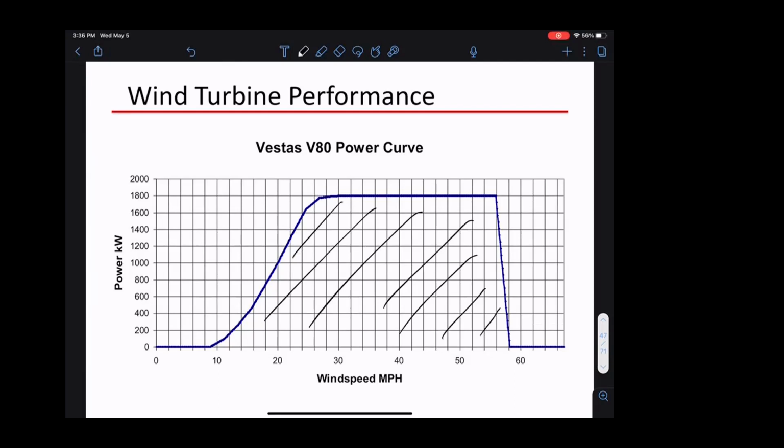So wind turbine generation is not entirely uncertain. You have some ramping capabilities, but your ramping capability is limited by the wind speed you're experiencing. Based on your wind speed, you can ramp somewhat, but not arbitrarily, and this depends on the external speed you have from wind. Any questions about these operating characteristics? Okay, so these are our operating characteristics.